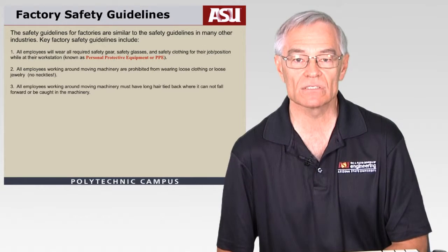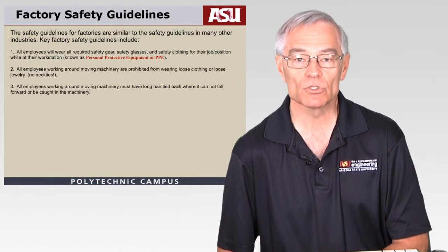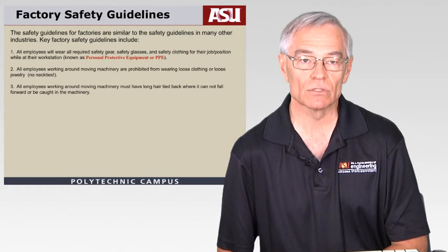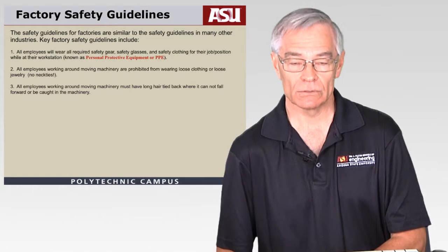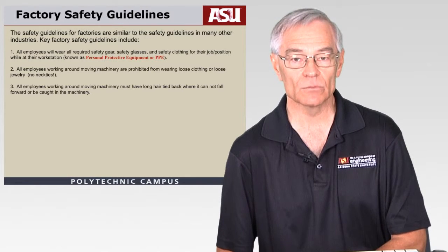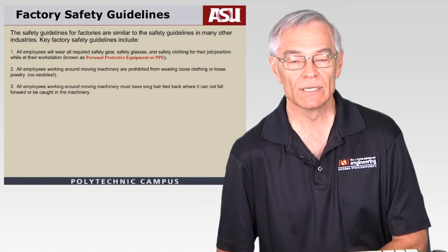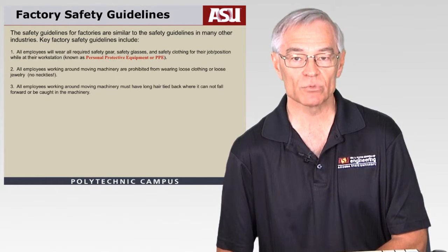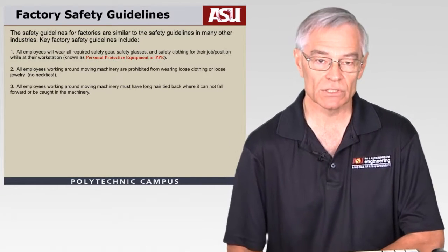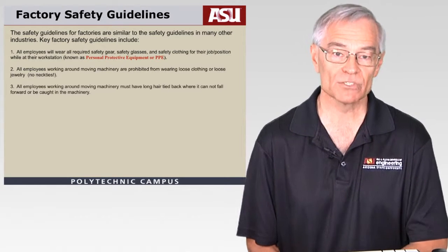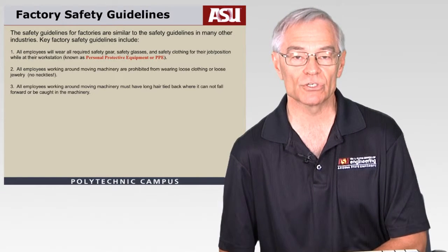We had a near miss in our manufacturing lab over in the Sim building when a woman who supposedly had been told multiple times not to have her long hair loose, did not have it properly secured, got her hair tangled in a lathe and was getting sucked into it. Fortunately, the lathe was turning relatively slowly, and so somebody could get to the emergency stop switch and saved her. Otherwise, it would have been a very severe accident, probably resulting in death. So we had a near miss, and then I think from then on, people took the idea of keeping your long hair properly secured much more seriously.